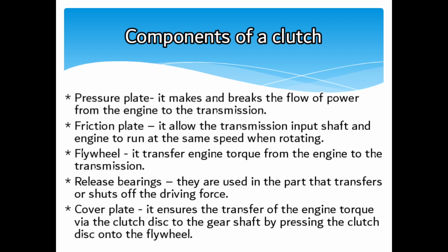Pressure plate, as its name implies, applies pressure to the clutch disc for the transfer of torque to the transmission. The pressure plate, when coupled with the clutch disc and flywheel, makes and breaks the flow of power from the engine to the transmission. That is the function of the pressure plate.